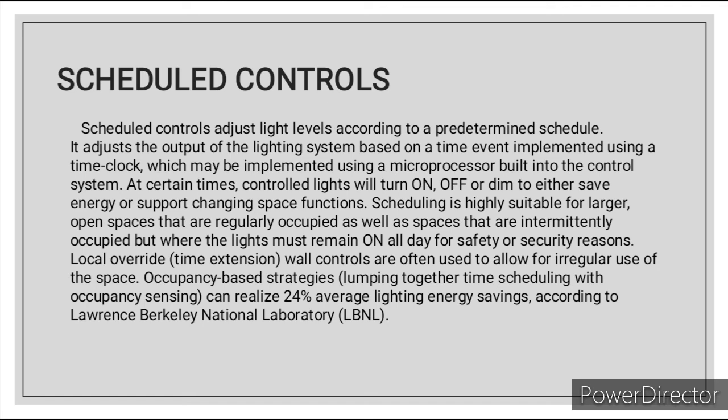Scheduling is highly suitable for larger open spaces that are regularly occupied, as well as spaces that are intermittently occupied but where the lights must remain on all day for safety or security reasons. Local override, time extension, and wall controls are often used to allow for irregular use of the space.